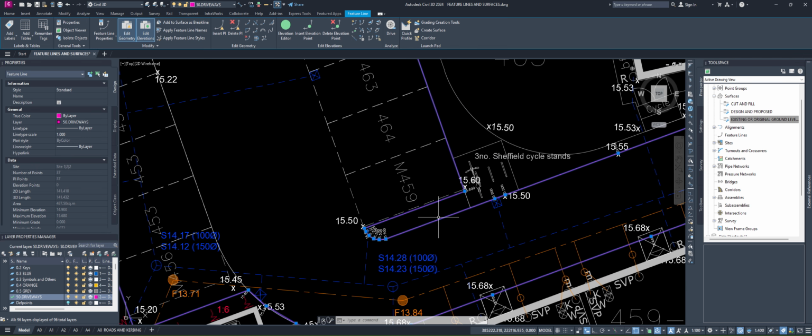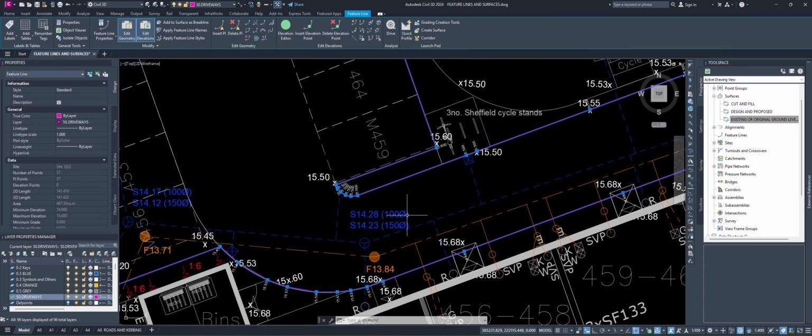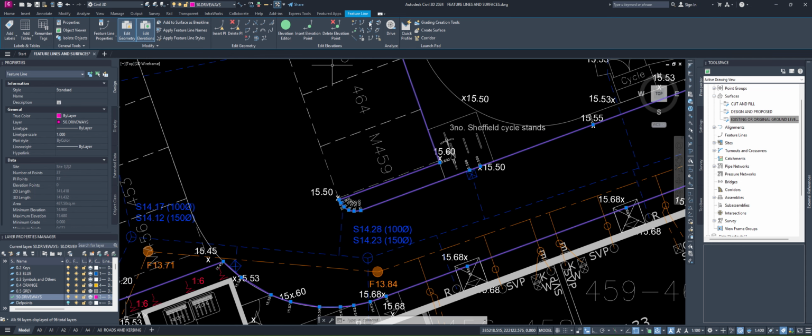So we're going to create probably a 50 mil high point. It won't massively affect our crossfall. It's actually going to help our crossfall be a little better structured. Okay, so let's go to insert elevation point, and we're going to insert an elevation point somewhere here. That elevation point is going to be 50 mil higher than that end and that end. You can add it somewhere here as well. It's not a big issue as long as you've got a high point at this end, which is working really well.